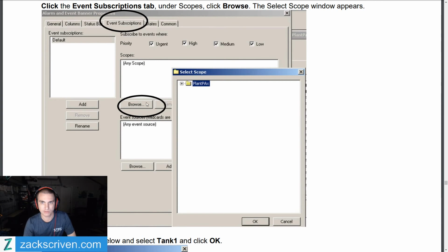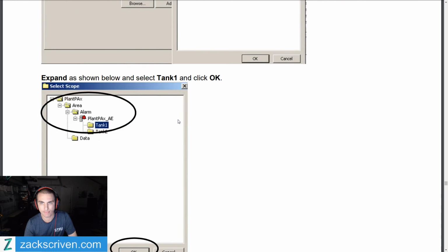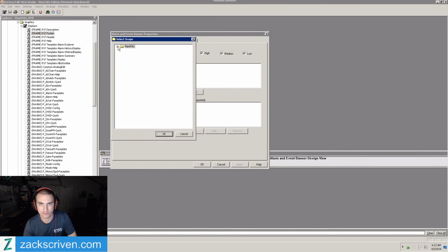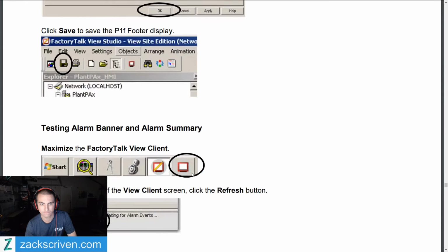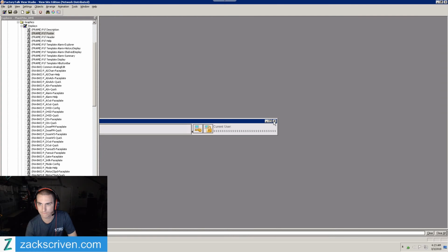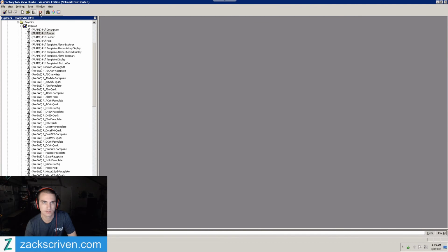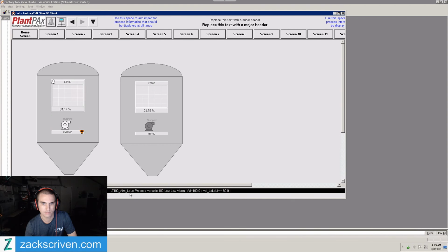Then go to event subscriptions, browse. PlantPAx, drill down into alarm, PlantPAx AE, tank 1, okay. Apply, okay. Hit save. For some reason I gotta close this. Yes. Save, okay. Alright, now we're gonna go back here. Now we see that there.